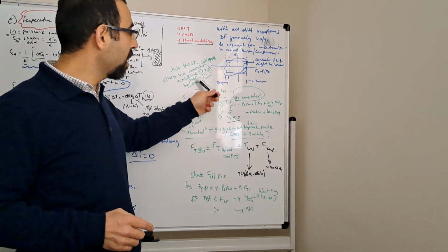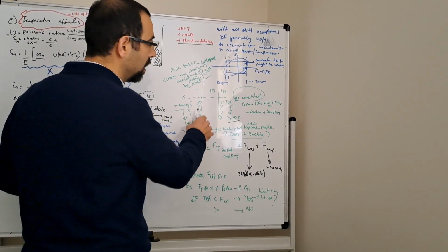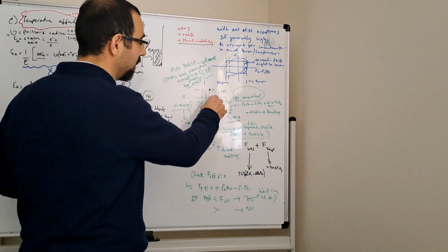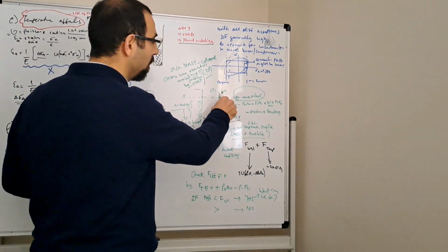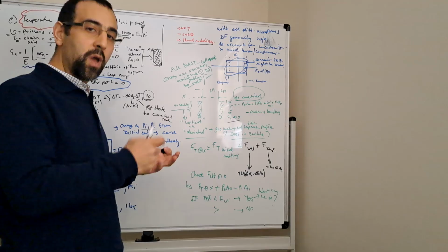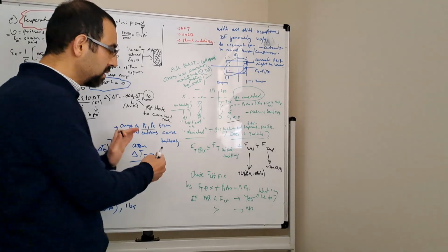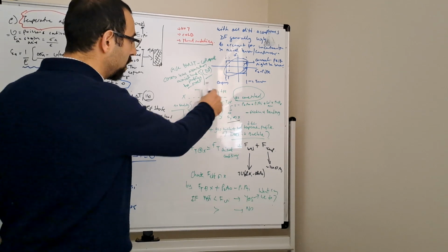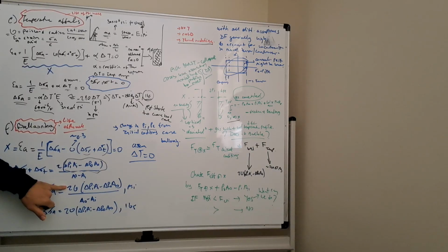And then at every depth you have this. So at every TVD, as I mentioned on the first page, you come up with your internal pressure and external pressure, and also the internal initial conditions, which is the cemented profile. You have the internal pressure and external pressure. So what you need to do is take a reference state, which is the initial conditions, and then take the final state, and then you calculate your ballooning force using this formula.